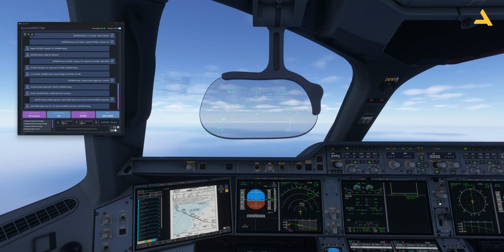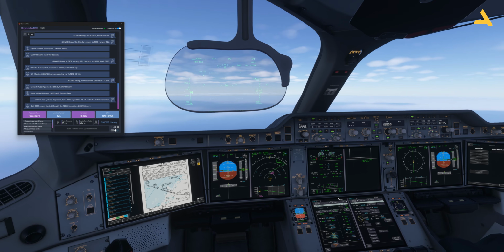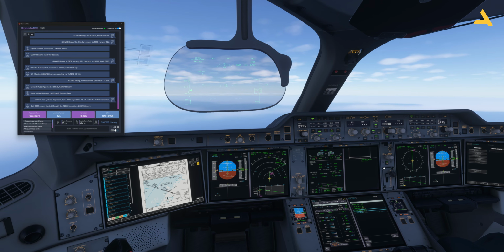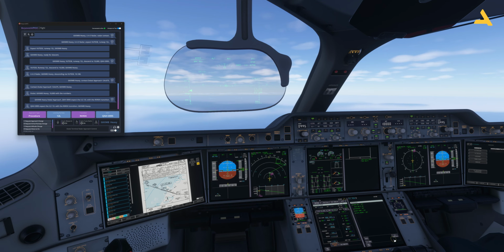Let's also arm the auto brakes, and I can bring up the checklist for the approach. So baro references set and minimum set, runway conditions dry, auto brakes. You can see it's set to dry. That's it. And auto brake set. Checklist complete. And now bring the landing checklist. I will keep it over here.